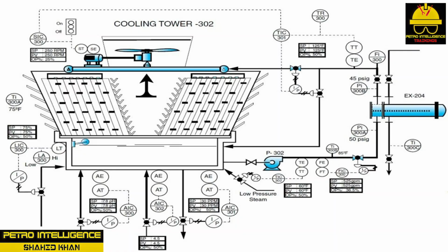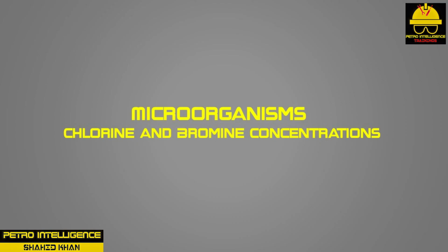Blowdown on CTW302 is timed so chemical injection has time to blend into the recirculation system. A chemical additive is added in a section of the cooling tower where turbulent flow enhances mixing and where it is not drawn into pump 302 suction before adequate blending has occurred.